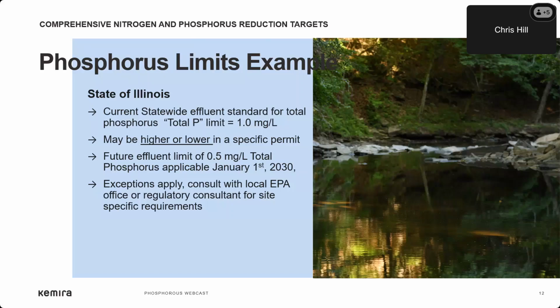While much discussion has occurred about the need for stricter phosphorus limits in the future, the current reality is that many states have adopted regulations limiting the allowed phosphorus concentration in wastewater effluents. It is common to see statewide regulations limiting those concentrations to 1 milligram per liter or less. Many discharge permits have a 1 milligram per liter limit, but there may also be future ultra-low phosphorus limits as low as 0.5 milligrams per liter, 0.2 milligrams per liter, or less.